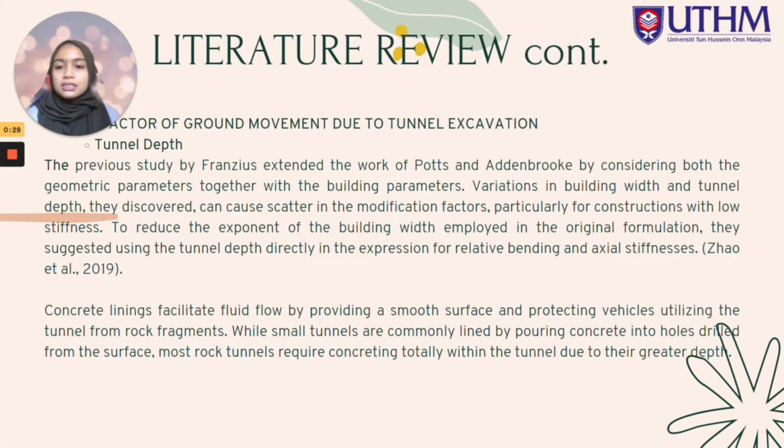Concrete lining facilitates flow by providing a smooth surface and protecting vehicles utilizing the tunnel from rock fragments, while small tunnels are commonly lined by pouring concrete into holes drilled from the surface. Most rock tunnels require concreting totally within the tunnel due to their great depth.